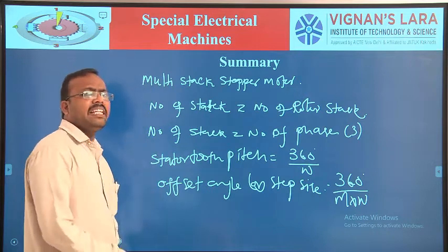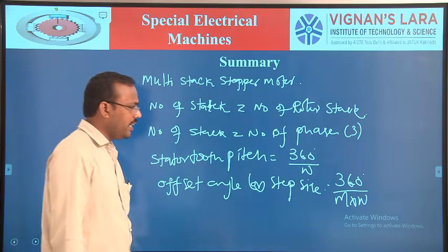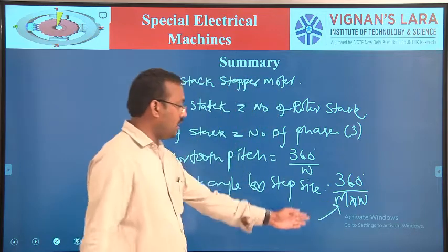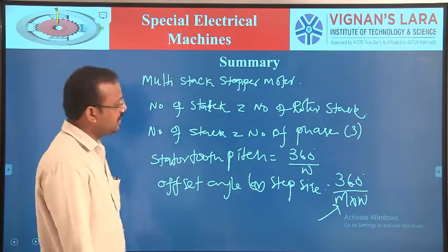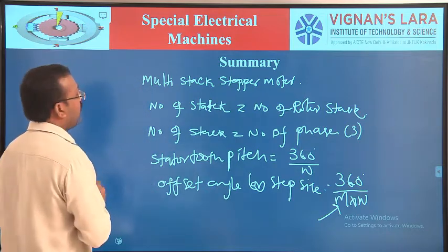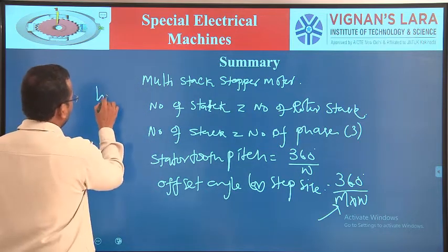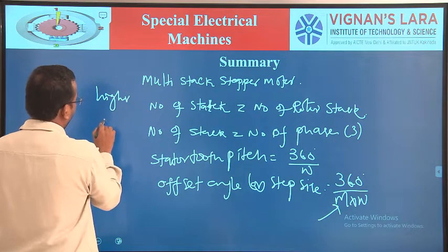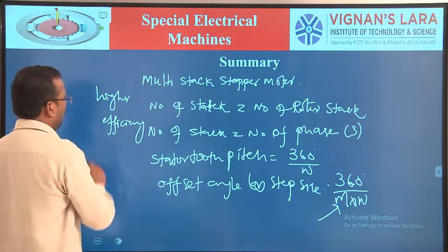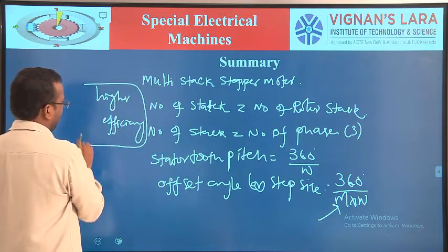So if you want to increase the step size, you can increase the number of phases m. The multi-stack stepper motor offers higher efficiency compared to the single stack stepper motor.